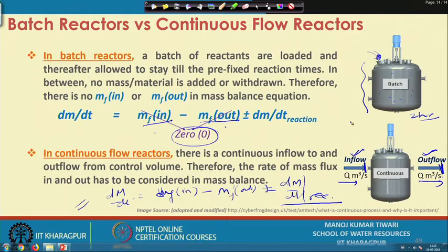or let us say there are two reactants needed, one we are supplying continuously and one we are putting in batch. So, those kind of intermediate processes are called semi batch processes, and we can specifically write the mass balance equation depending on which substance, which contaminant we are targeting in such systems.